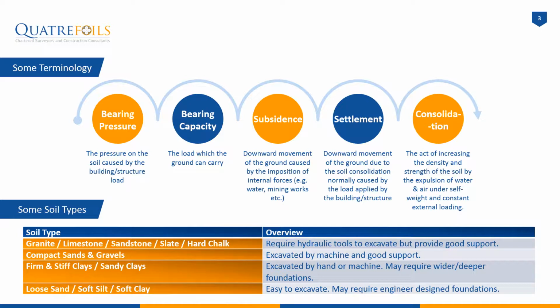Next we have firm and stiff clays, and sandy clays which can be excavated by hand or machine. These may require wider or deeper foundations depending upon the exact build-up and bearing capacity. Last we have loose sands, soft silt or very soft clays. These are very easy to excavate but are likely to require specialist engineered designed foundations.